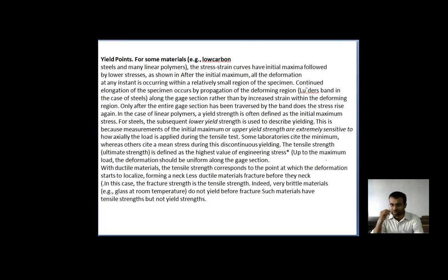So that particular such materials are taking place in that particular figure, which I showed earlier. Some of the most important considerations involved in tensile testing include the sample selection, which is to be taken care of by the ASTM standard, and the sample preparation, which is also followed by the ASTM standard. The test setup and the test procedure are also according to that ASTM standard, that is, how that particular material is to be tested. And then the data recording and the analysis, and the reporting.